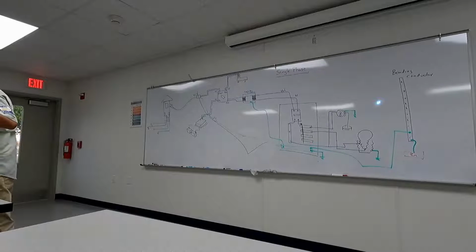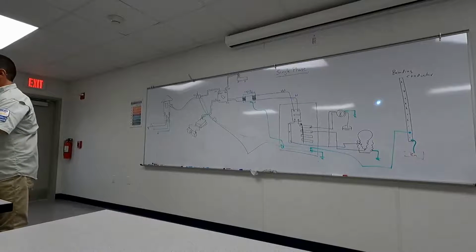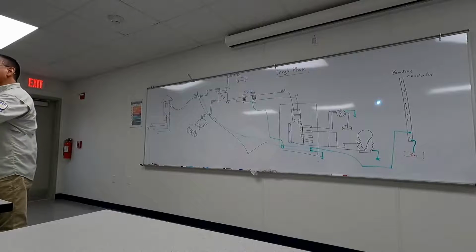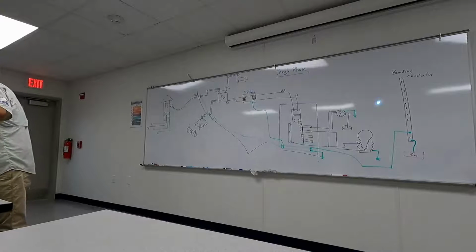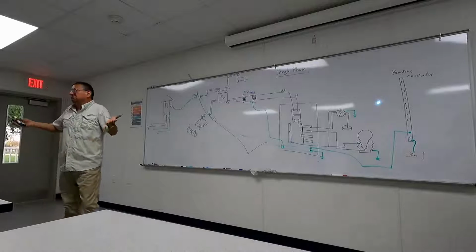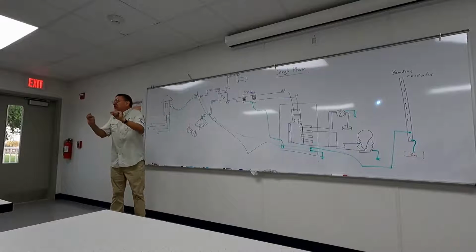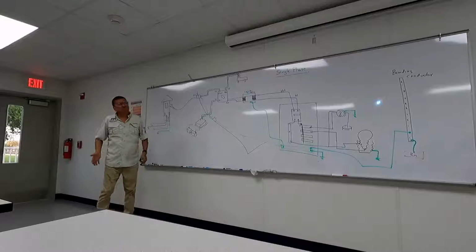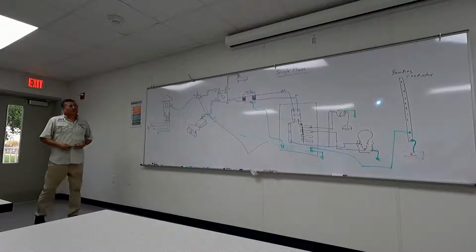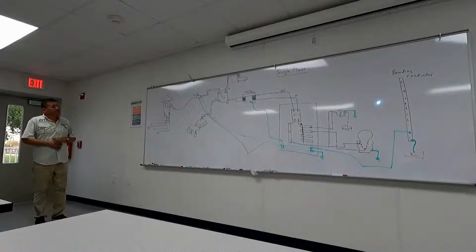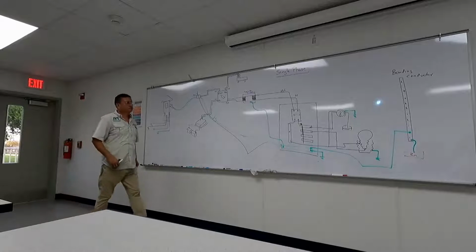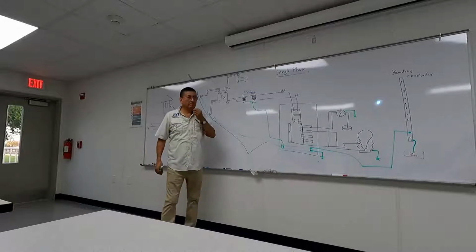Only use 5200 if you plan to never take it out again. Let me tell you how strong 5200 is. If anybody doesn't know what it is, it's like a super glue. It's not silicone. When we put swim platform brackets on the back of boats to hang outboards, we use 5200 because I don't want it to come off. This guy had a problem with his bracket after many years because he had electrolysis.